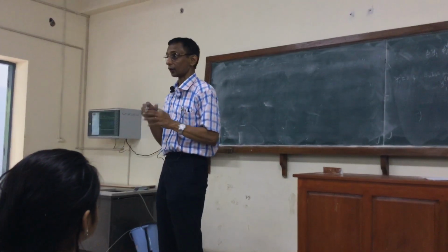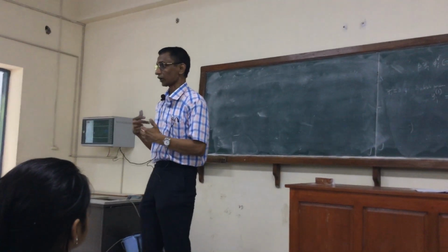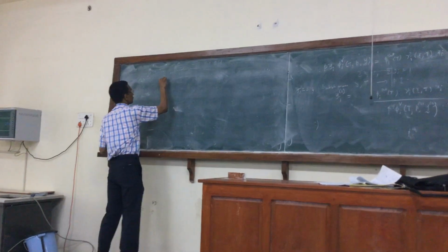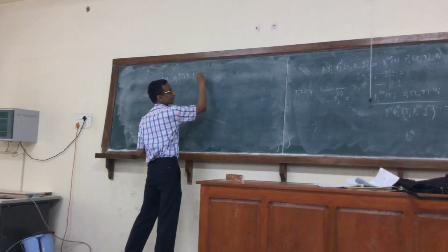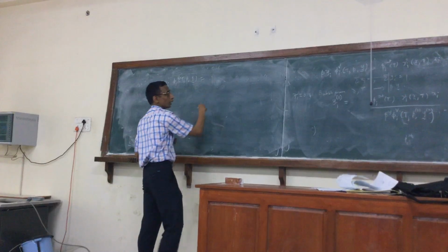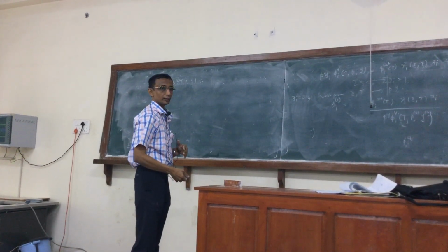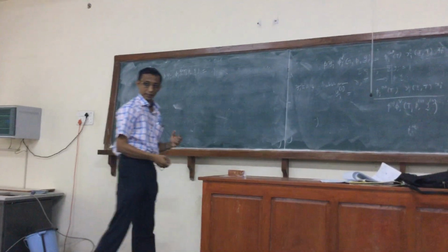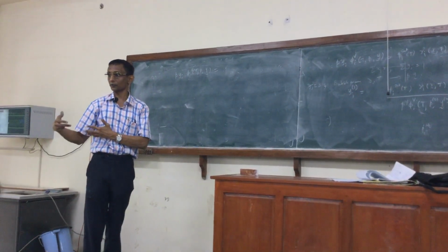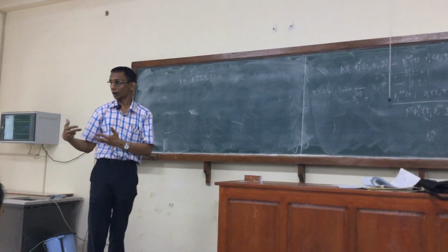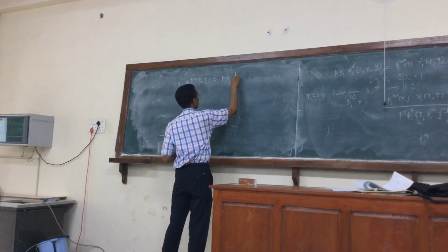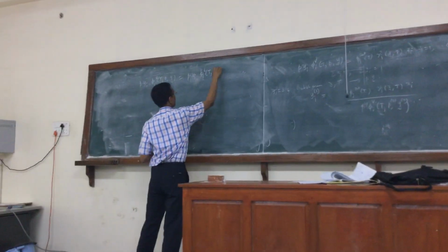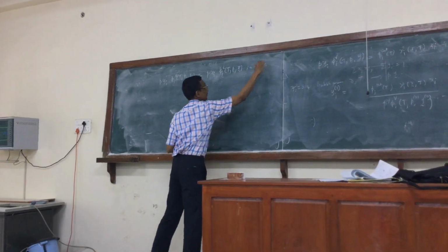Construct the working formula to calculate the mole fraction. But that's not all. There's another aspect: we will also check the mole fraction constraint. So here, the difference would be Pyi. The right hand side remains the same. The left hand side is going to be, again, the fugacity of the liquid. The component i in the liquid is also expressed in terms of fugacity coefficient, and the equation of state, not in terms of the activity coefficient model. So here again I have Pxi phi iL of Px, sum i equal to 1 to C.